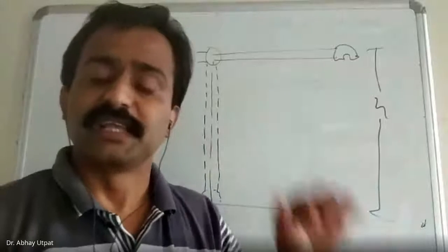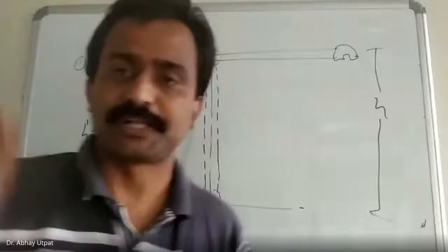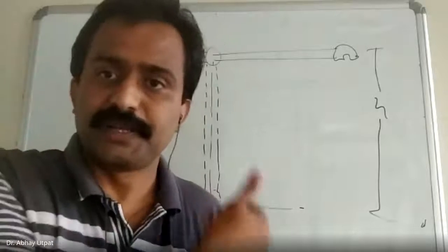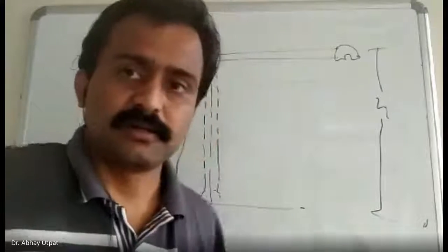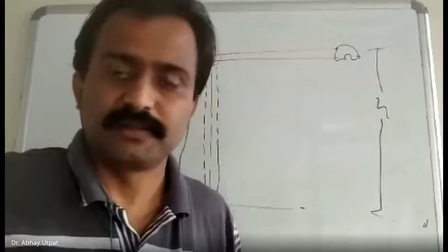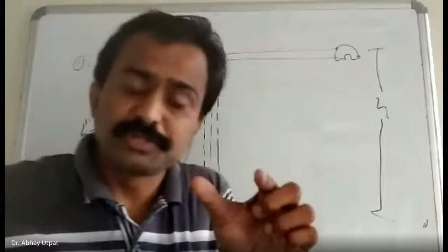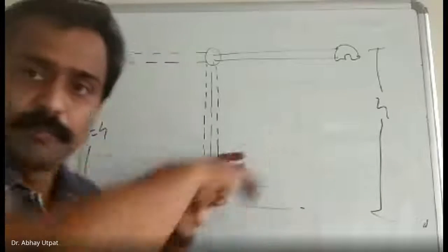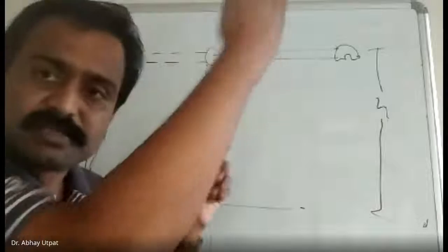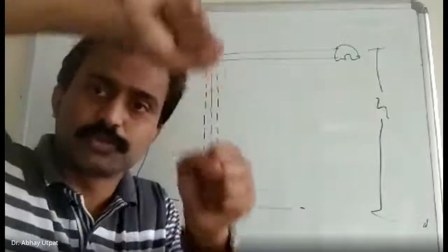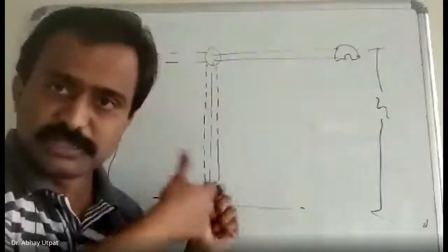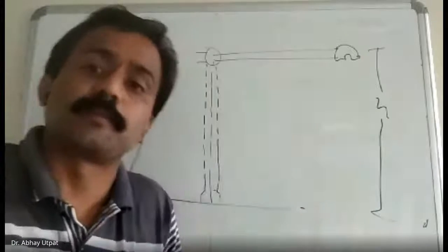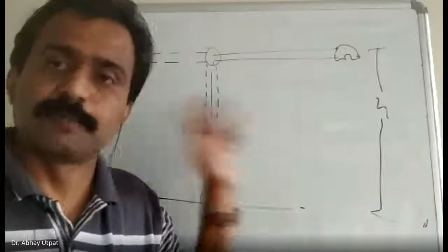Toughness is energy absorbed prior to fracture. It is the relative toughness obtained from this impact test experiment. So the specimen which you are using is of MS, mild steel, a ductile material, but it breaks into pieces. The same mild steel was used in the tensile test, it was showing elongation. Now we have changed the shape and it breaks into pieces. So a ductile material fails in a brittle manner, as checked by this impact test.